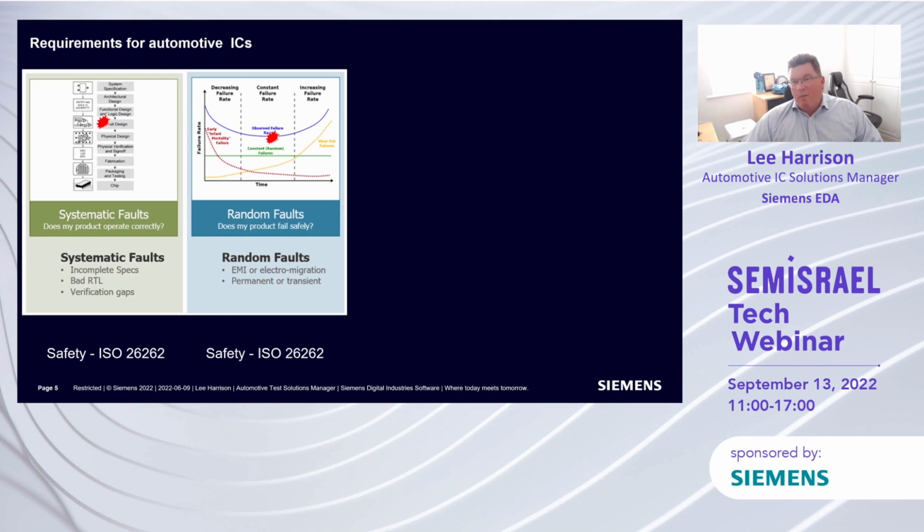So whether that's a physical fault that just appears through the aging or degradation of the silicon, whether that's a fault caused by any other environmental issues within the vehicle, or even if it's just what we call a transient fault, where stray radiation particles pass through the device and have the potential to flip bits and digits within the device, which could cause the device to malfunction.